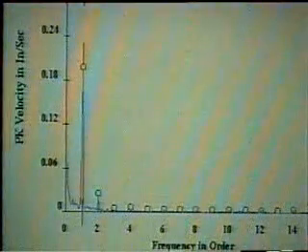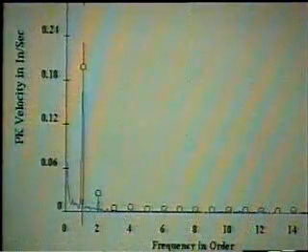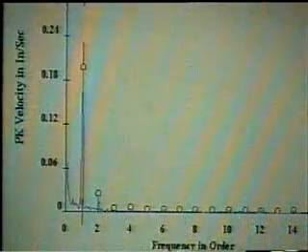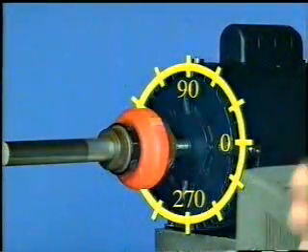The signal from the sensor is sent to the strobe light, causing it to flash at the rate of the vibration. In order to use this method for diagnosis, either the signal must be dominant at shaft turning speed, or it must be filtered to cause the strobe to fire at the shaft speed. The rotor must be marked with either a reference mark or the angles.